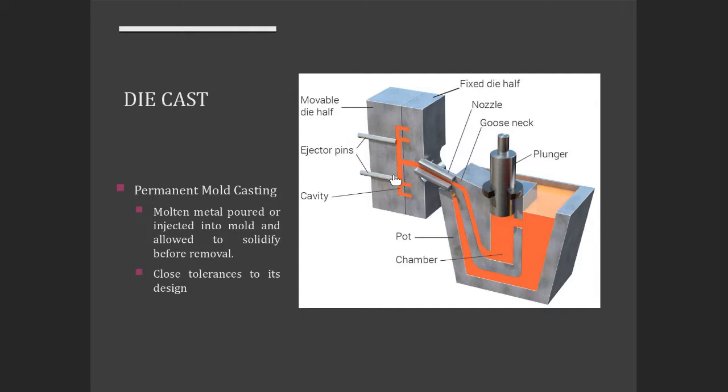The only problem is you have to wait for it to completely solidify in order for you to then remove this piece, and then these ejector pins will then push your portion out, and then you'll just cut those off later.